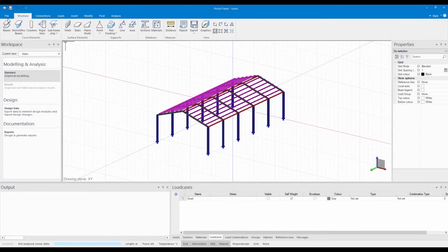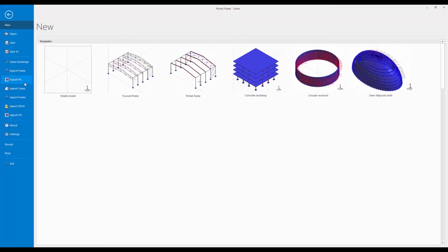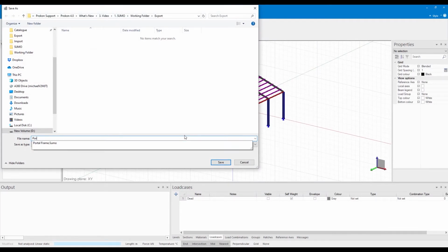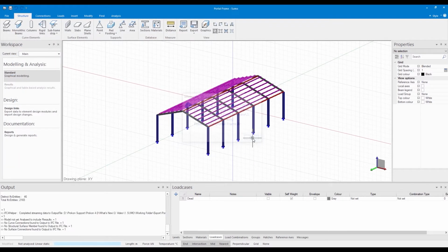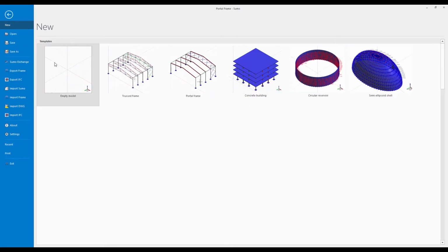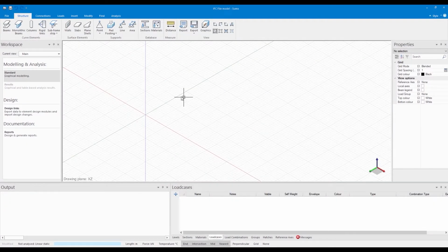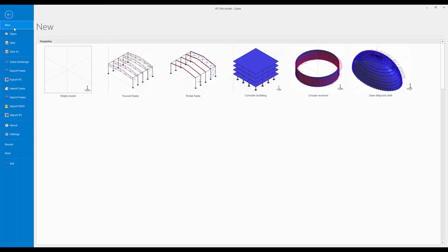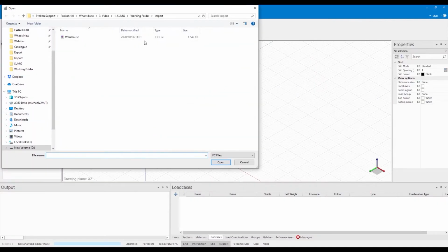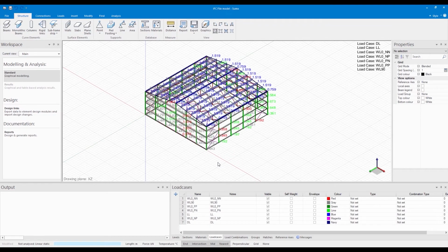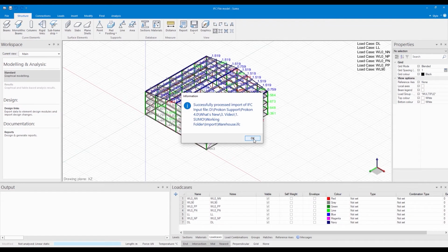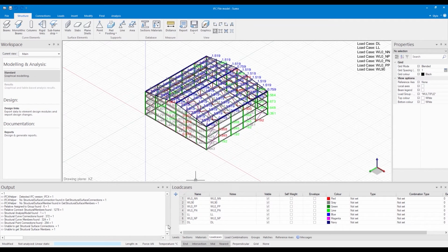Sumo Structural Analysis has further developed in order to maintain its compliance with the Building Information Management strategy by becoming compatible with industry foundation class files. The module now allows the importing and exporting of structural analysis IFC subsets with other third-party software. To ensure a seamless integration, when exchanging structural analysis IFC subsets, the module displays an information box indicating the success of the import or export and an output dialog box which supplies the user with a list of detailed information regarding the exchange.